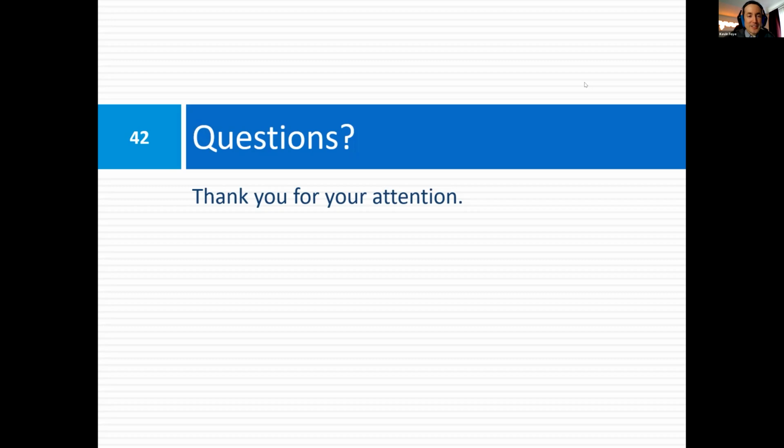Okay, yeah, what kind of monitoring? So this is the same kind of question. What they do at this site, there are two technicians who essentially work every day at this site, and their job is to walk the site and look for signs of distress and to document them, to survey them, and to map them. And if it looks like that will impair the ability of the final cover to drain, then they have to go out and at least fill in the superficial ponding.